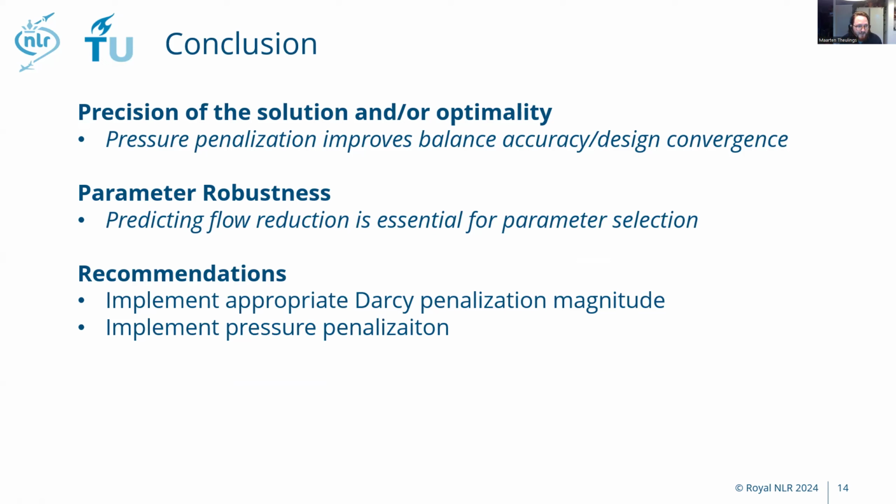Yes, but there's one problem, a slide that I have here. I also checked that flow reduction for varying elemental Reynolds numbers. And I looked at the low Reynolds numbers, where I have that penalization that always works. So when you're sure that your elemental Reynolds number is always smaller than 1, you're fine. But when it's bigger than 1, I tried two things. I tried the standard one, the one for the lower elemental Reynolds numbers, that's the dashed lines, and the solid lines. And there I found that with the solid lines, with the penalization that I define, it reduces the flow error still a bit.